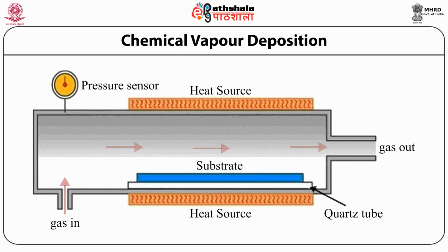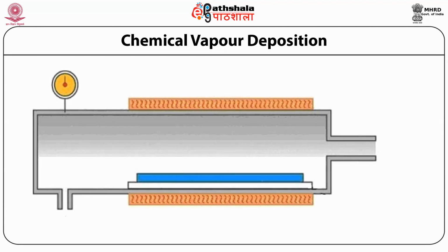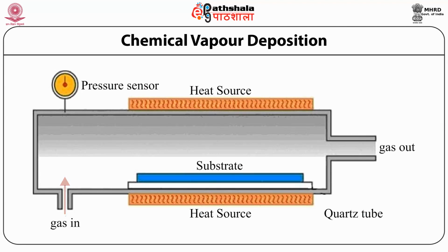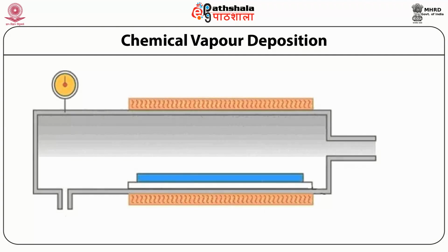The chemical byproducts or unreacted gases are then eliminated from the reactor chamber via the exhaust system. CVD must take place under a vacuum to avoid inclusion in the film, or creation of side products, from the reaction of the ambient components with the precursor gases.